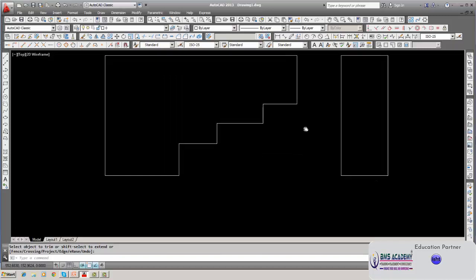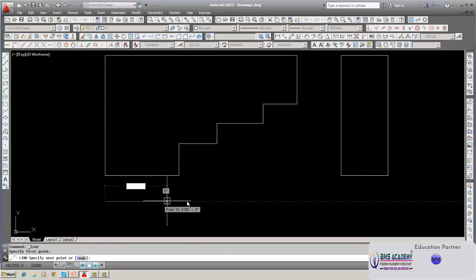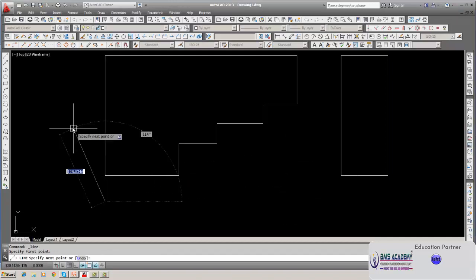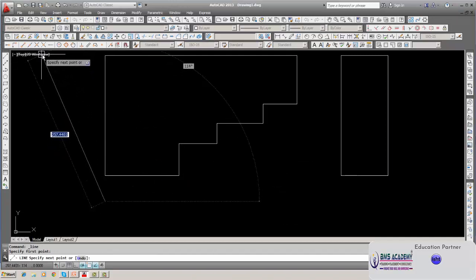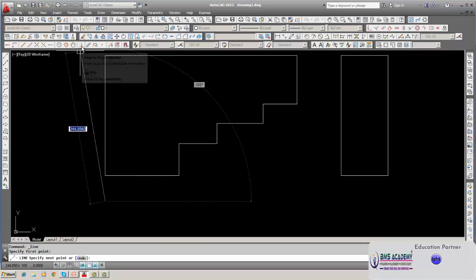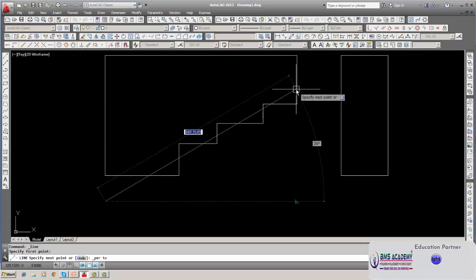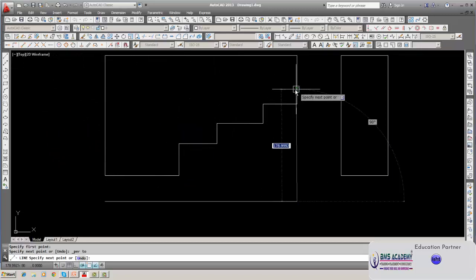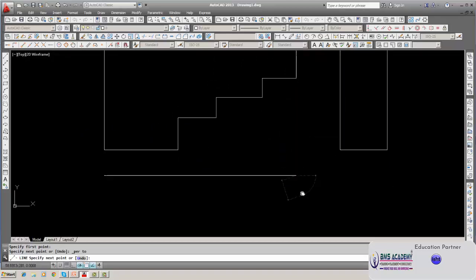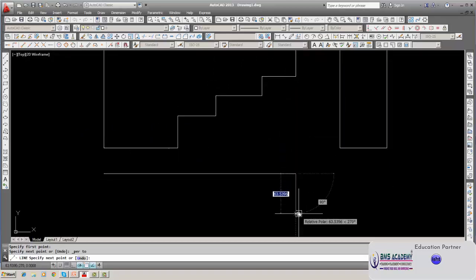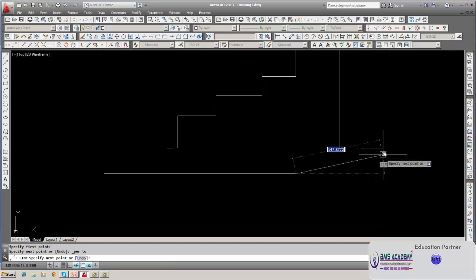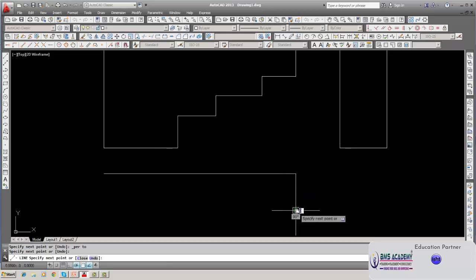The bottom view also we can draw if necessary, but for simplicity we will draw the bottom view also, to show how the job looks. Then select the perpendicular line somewhere here like this, and the line extends only up to that point.